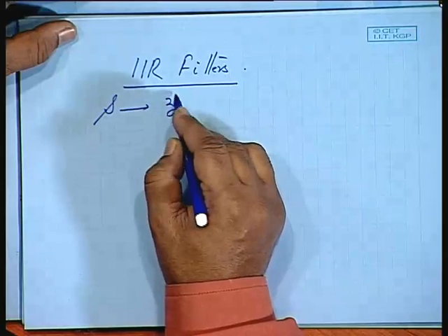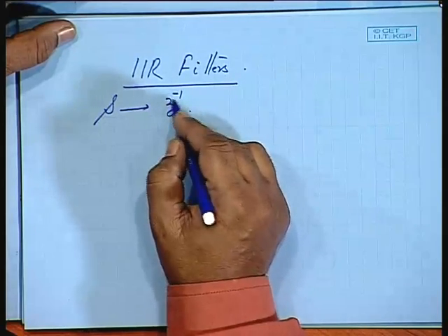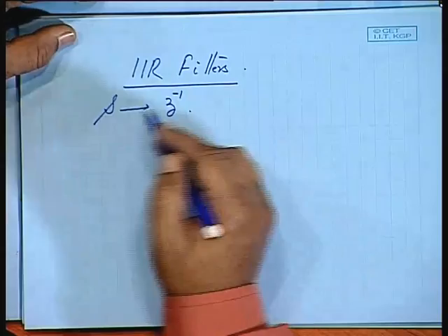of Z, or in terms of Z inverse. If you can express S in terms of Z inverse, then you just make a substitution for S, that function of Z, and then that becomes the filter. Now, we shall be taking up some of the simple substitutions that can be made and then see the limitations of different substitutions, and then again we will come back to a little details of analog filter design.